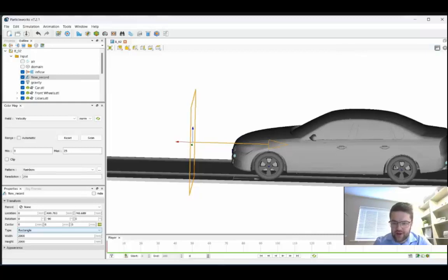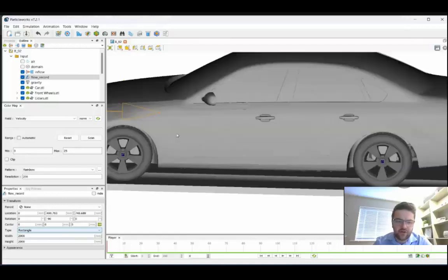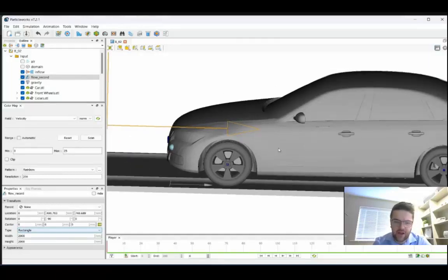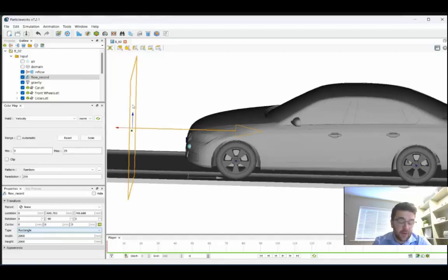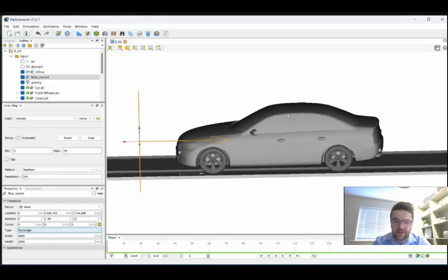And then that just creates the inlets on these planes around the car, to then see how the subsequent changes to the car, so a little feature here, mudguards, whatever else we've added on, are affected by the incoming particles, because nothing's going to have changed far away from the vehicle just because we've added something here. So yes, we can keep that little boundary condition exactly the same for all simulations and massively cut down the overall simulation time. Okay, that answers that question.